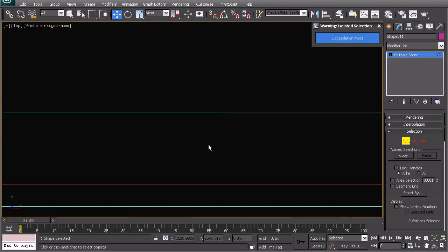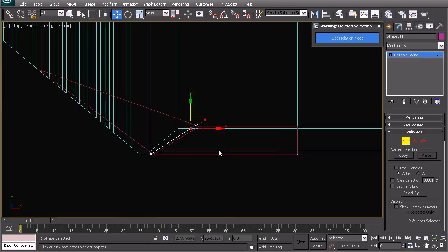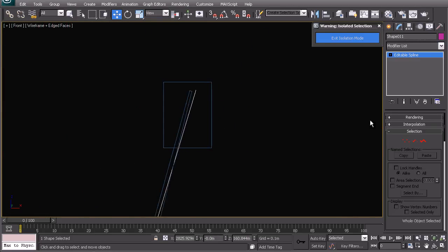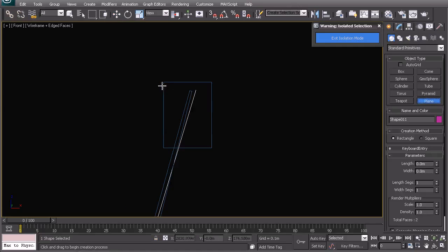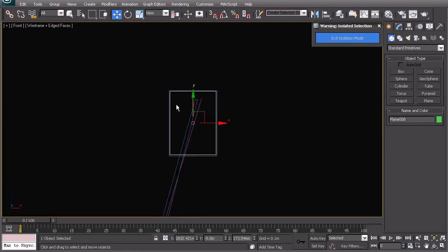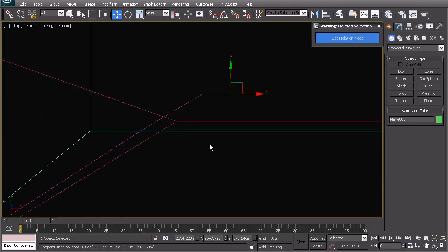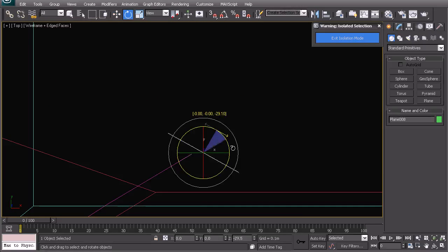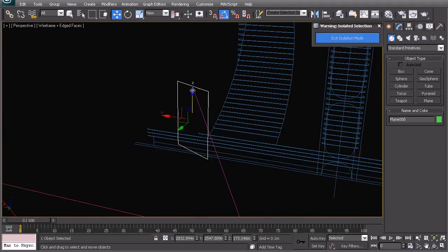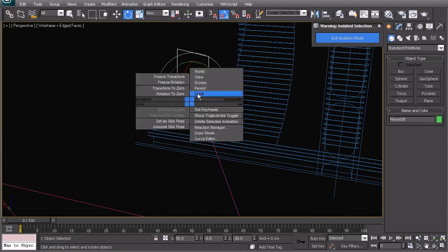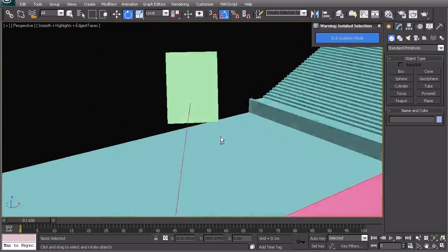Now let's go into plan, and let's edit that as well to just look like it's a pole that's coming out. Now let's go back into the front view and let's create a plane that is going to be sitting here. I'm going to snap it to this object so that when we go into top view we can immediately be in the right area, and we just visually adjust this however we feel fit. We can Alt right click and choose local so that we can tilt it downwards. And this will be the base geometry for your lighting.